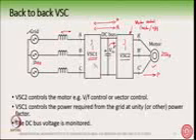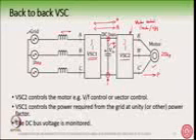So suppose now we have VSC1. VSC1 can know how much power it needs to give to VSC2 by monitoring the DC bus. If it just monitors the DC bus, it will know how much active power it needs to send to VSC2. Remember, VSC1 and VSC2 don't know each other. They are not communicating with each other. VSC2 only sees the motor and is exclusively used for motor control. VSC1 knows how much power VSC2 requires by sensing the DC bus voltage.